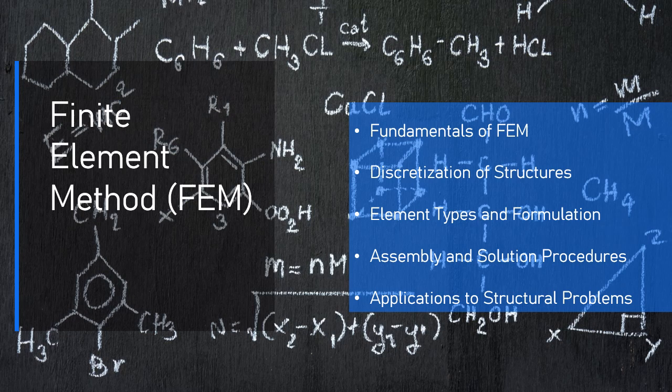7. Post-processing. Once the displacements are determined, internal forces, stresses, and strain within the structure are calculated from the displacement field using the element stiffness equations. These can be used to assess the safety, stability, and performance of the structure. 4.2. Advantages of FEM. Versatility.